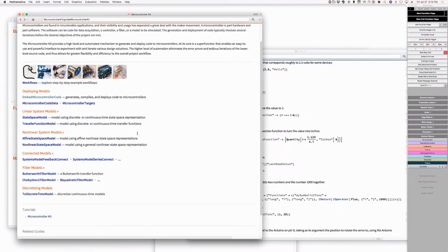But a typical thing would be, if the plane is at 38,000 feet, and it's a certain speed. The envelope is typically parameterized by speed and height. And what about on a plane, if it puts its flaps down, does that change things, the configuration of the control surfaces? No, the flight envelope is just parameters like angle of attack, velocity, the height, and so on. And then there are hard limits on how far the control surfaces can go.